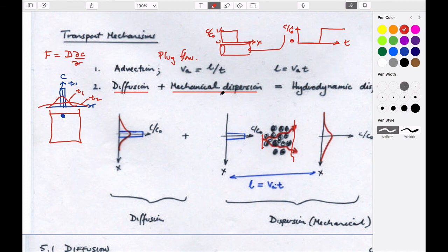And so mechanical dispersion is something that looks like diffusion, because if you didn't know that you traveled downstream, but you thought you're still in the same location, you'd think it had just diffused. But the mechanism by which it's done this is by this tortuous spreading. So the flow paths of the water as it goes downstream have gone down these different pathways. It's meant that it's carried the solute with it, and so that downstream it looks like this. And so advection and dispersion, but often these are termed just dispersion,